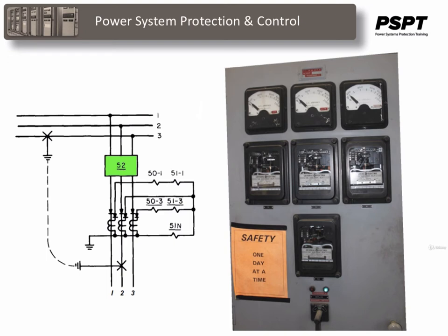On 3-phase 4-wire systems, which represent a large percentage of the new installations, it is not always possible to balance perfectly the single-phase loads among the 3 phases. The use of sensitive residual ground overcurrent relays may not be feasible if the relay picks up under normal load conditions. For such systems, the 3 overcurrent relays are often connected in the phase circuits of the current transformers, and the sensitive ground fault protection is sacrificed.